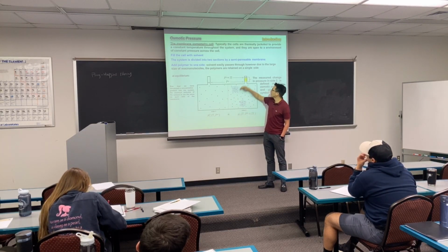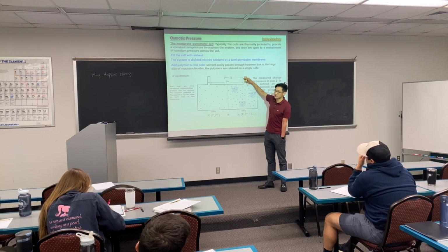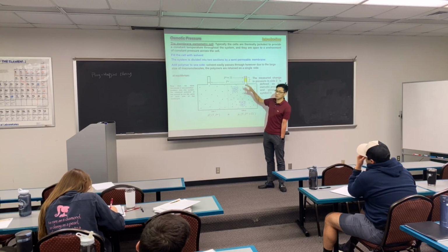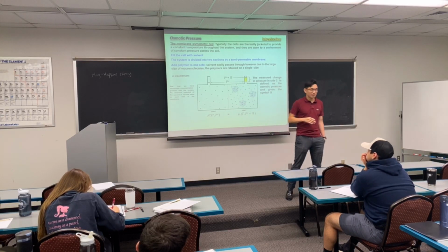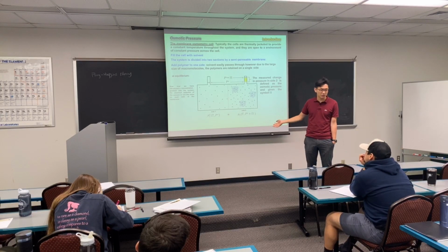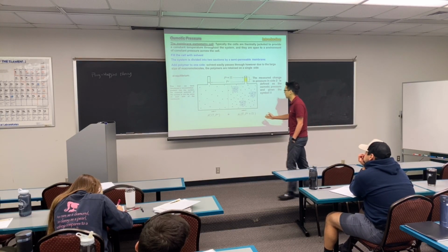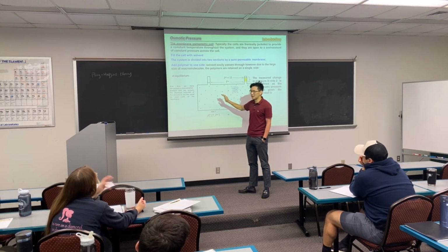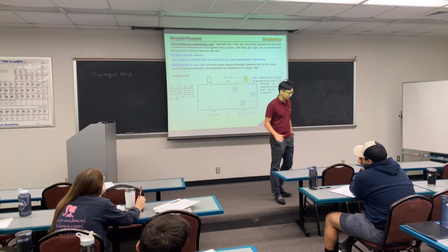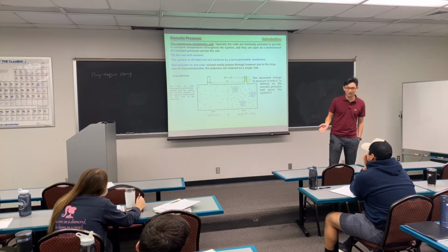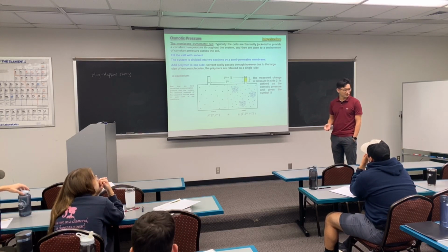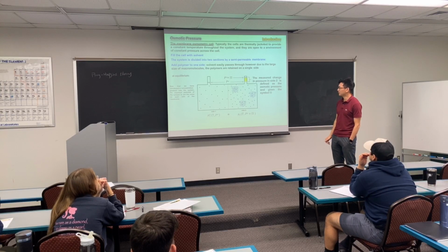They put a membrane, they put a high pressure pump to squeeze the water molecules there. Of course, you need to fight osmotic pressure and the energy of mixing or entropy of mixing, but you can actually drive it to create pure water on the other side, which apparently is one of the major reasons somewhere like Israel they can get fresh water. They just draw the water from the ocean and get it down.